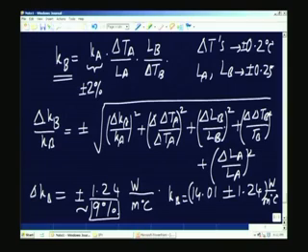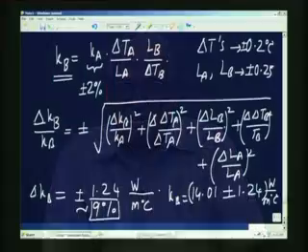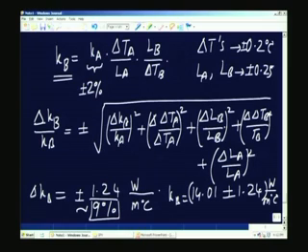We can also discuss this error by looking at how we can reduce the error. For reducing the error, what are the sources of error? Sources of error, of course, the measured values. The Ka we have no control because Ka has got a specified value of 2%. It is the delta T's which need to be measured more precisely. If we can measure the temperature differences much better than plus or minus 0.2, and also the locations of the thermocouples are more precisely known, I think we improve the accuracy of the measurement of the thermal conductivity of the material B. By suitable improvement, if we can bring it down to about plus or minus 5%, that will be acceptable for most engineering applications.